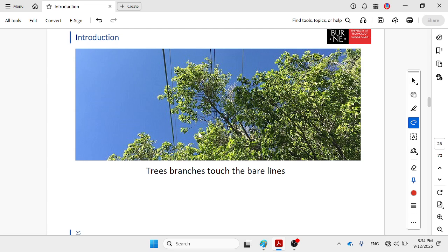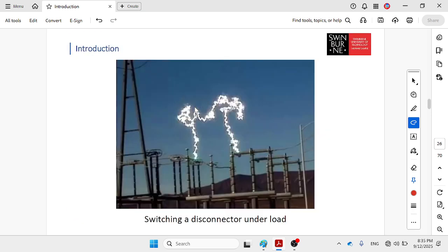The trees, as I mentioned, also, because inside the tree we have water, and the water is conductive, and we have mineral water also inside those trees. So if any wire or any branches of the tree touch the wire, that branch is electrocuted, and the energy and the electricity is sent to ground, and the system considers that one as a fault.